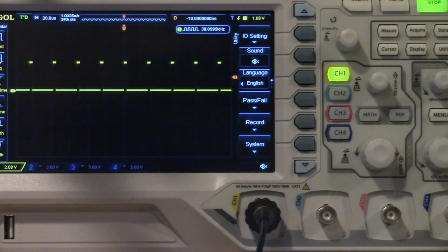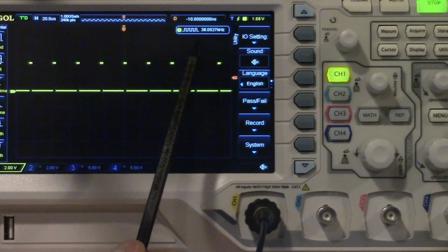All right, so you may remember that in our initial experiments generating square waves from the FPGA, we were having trouble getting a solid frequency output from the FPGA. It kind of was a little bit too high and the frequency sort of varied. So I am now working on generating synchronization signals for the VGA monitor, and right now I'm trying an experiment to generate horizontal sync, and the horizontal sync frequency for the 800 by 600 60 Hz SVGA mode should be precisely 37.8787 kilohertz.